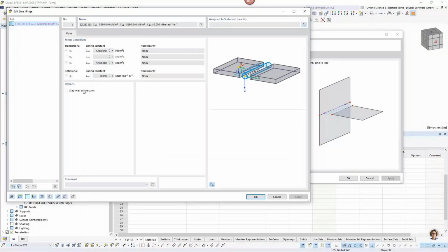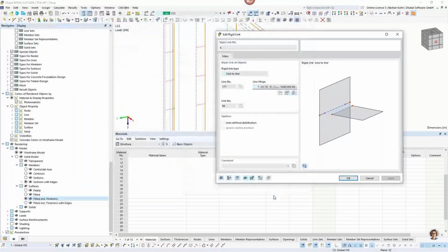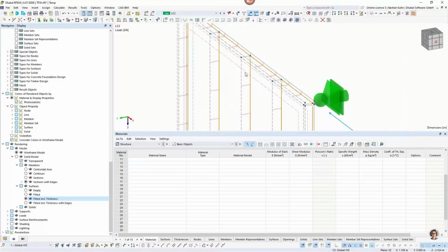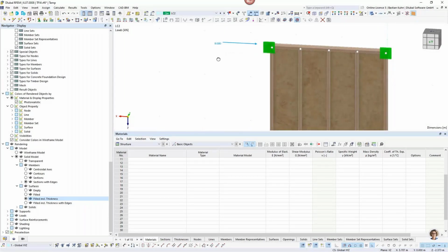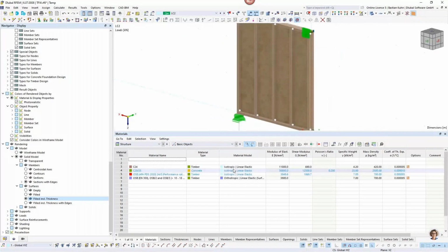I also told you that we should remember this longitudinal stiffness, where if I had chosen just to have the stiffness in ux direction, my uz value would be 0 in here. So that would also be possible. This is the generated hinge, and it's generated once again between each beam and the OSB planking. I will put on the rendering again. So here this way, it's probably a better visibility.